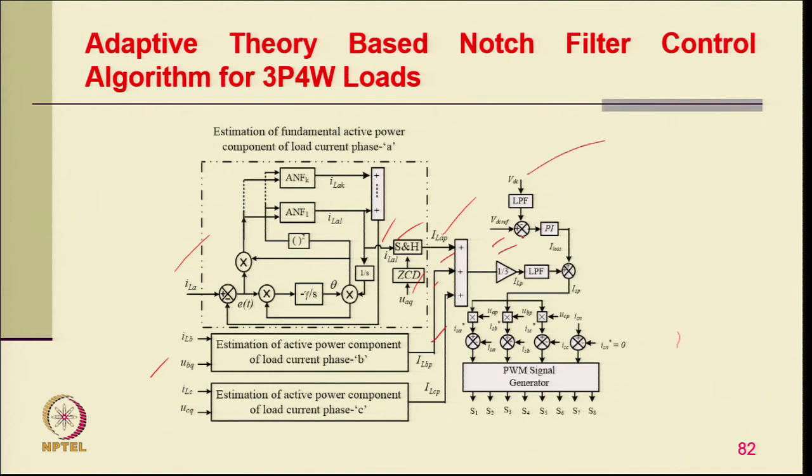We have DC link voltage regulation. Certainly, the DC link voltage has some ripple, a second harmonic ripple, for load unbalancing. That is the reason we use a low pass filter. Then we use PI control, which provides the loss component, and this provides the load. So, the total active power component has to come from the generator, and multiplied by the template, we get the reference generator current, and with the feedback of generator current we give the gating signal for the voltage source converter of the compensator.